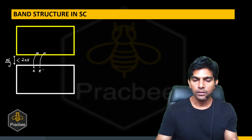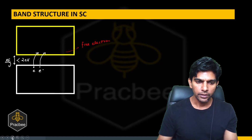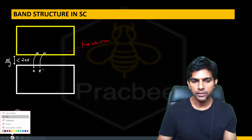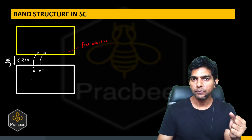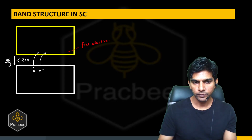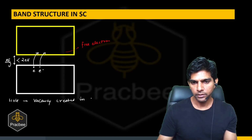When an electron moves from the valence band to the conduction band, we have free electrons or conduction electrons which can take part in the conduction process. And there is one more thing happening in a semiconductor. When an electron jumps from valence to conduction, a vacancy is created in the valence band, which is known as a hole. Hole is the vacancy created in the valence band when an electron moves to the conduction band.